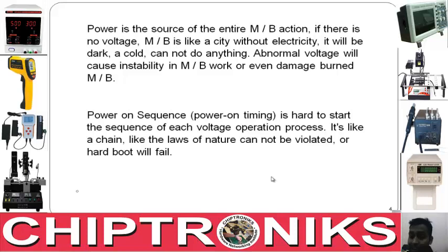Current may vary. Current will vary according to the application you are running, right? If you're running graphic-intensive work on a notebook motherboard, then the CPU will need more current, but the voltages would always be fixed, and that makes the life of a technician very easy, because we have to just check the voltages, right? If the entire notebook motherboard receives its required voltages while starting, then the hard start is finished, and then the soft start will go on.